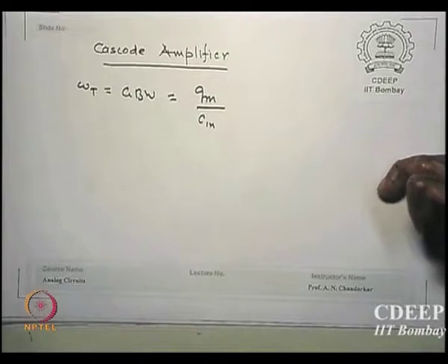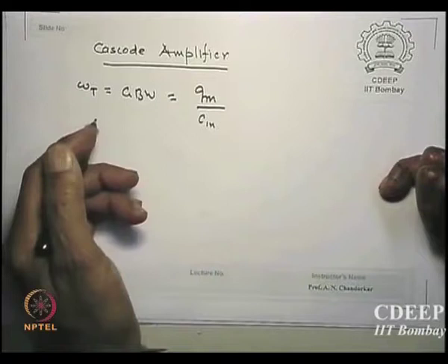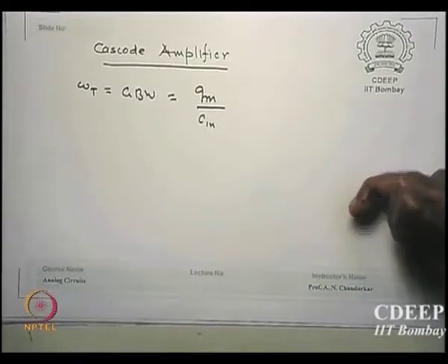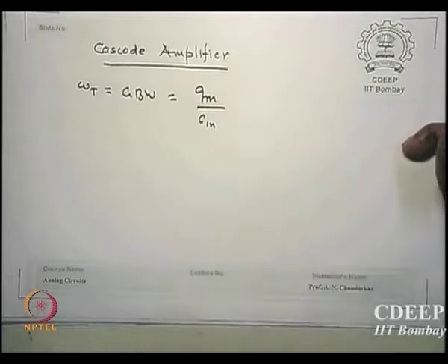So if I increase gain, I reduce bandwidth. If I increase bandwidth, I reduce gain, because this is fixed. Is that clear? But that is the limitation, you said, no? So essentially that is the maximum frequency up to which one gain at least should be seen. You can't go beyond. Now this is creating a problem. I want larger gain, but I don't want bandwidth to be lost.